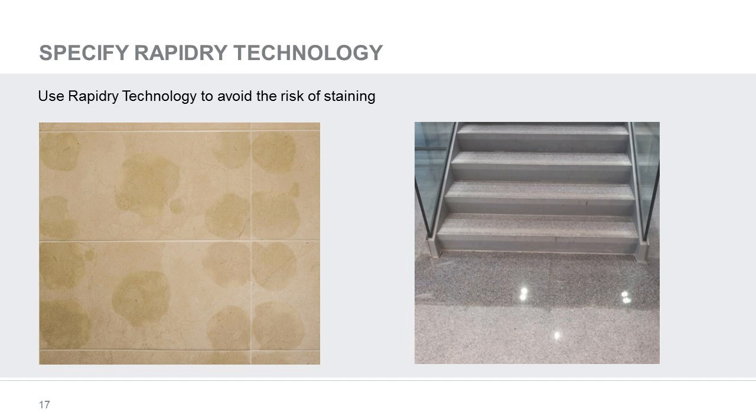However, the problem of water staining into the tile can be avoided by the use of a rapid drying technology mortar or an epoxy and grout designed for use with natural stone. The rapid drying formula system binds the mixed water with the mortar or grout, virtually eliminating the risk of water staining and guaranteeing the best possible finish to all natural stone applications. This rapid drying formula should not be confused with mortars which solely have rapid setting or rapid hardening.